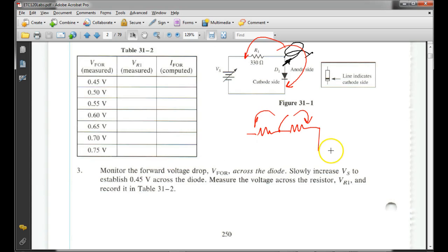We can't do this with a scope probe. These scope probes, guys, are referenced. That right there is referenced to earth ground. So you can't probe this anywhere you want to, right? Now, an isolated circuit that is not grounded, you can hook one probe in there and then you establish a ground, which can be anywhere.